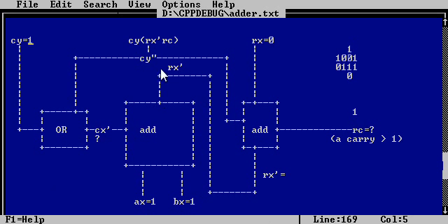Next, this is 0. So there's a 0 feeding into here, into my adder, plus the 1 carry. So 0 plus 1 going to the adder, which is essentially an XOR, makes this into a 1. And since there's a carry left over from here that goes into an OR, we get a carry. So the answer is 1 for a carry.